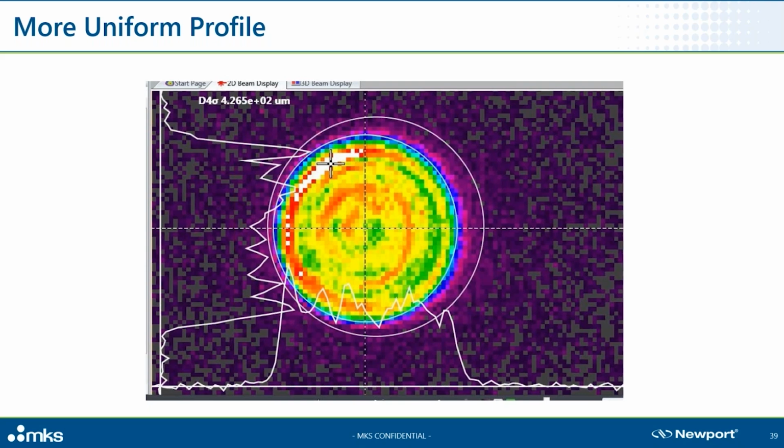So that's exactly what, in this case, the laser service technician was able to do: rotate the laser crystal to a more optimal alignment, and the beam quality improved greatly. It still doesn't look pretty necessarily, but if you look at the X and Y profiles, you can notice that they are all within a certain range. This indicates that it is a reasonable flat top, and this was confirmed through experimentation that the welder started to perform better.